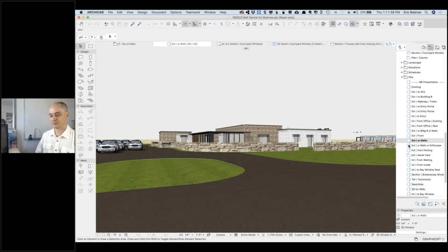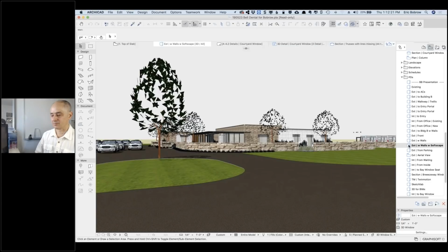This is actually a good view. He wanted to do a screen around the air conditioner condensers on the roof, and it would have been a complicated structure and have issues with engineering and windstorm. So I showed him this view. It's actual, it's 5 foot. I showed him if we just extended those two walls up 3 feet, it would accomplish the screening and be much simpler. And there we had the trees. Okay.